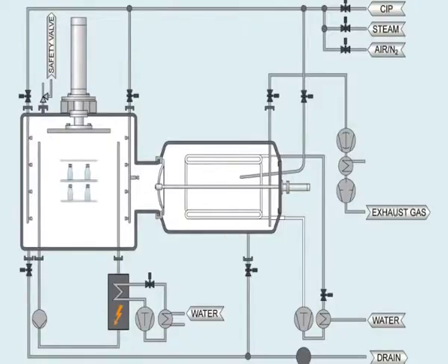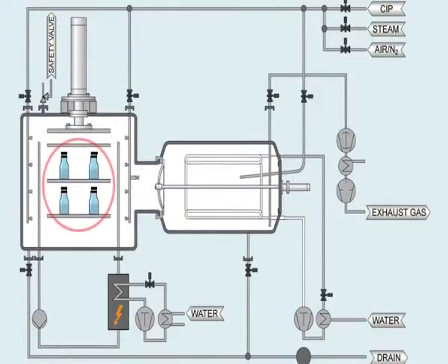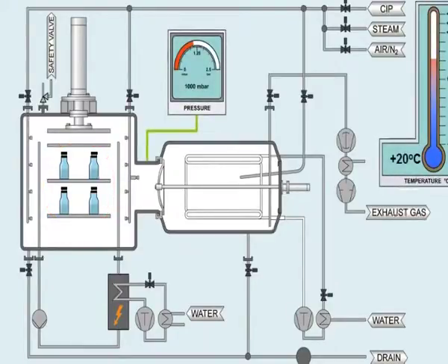First step is the preparation and pre-treatment. The volume of the solution introduced into the container is limited by its capacity. Therefore, pre-treatment is essential. The solutions are pre-concentrated under normal vacuum tray drying. This reduces the actual drying time by 8 to 10 times.